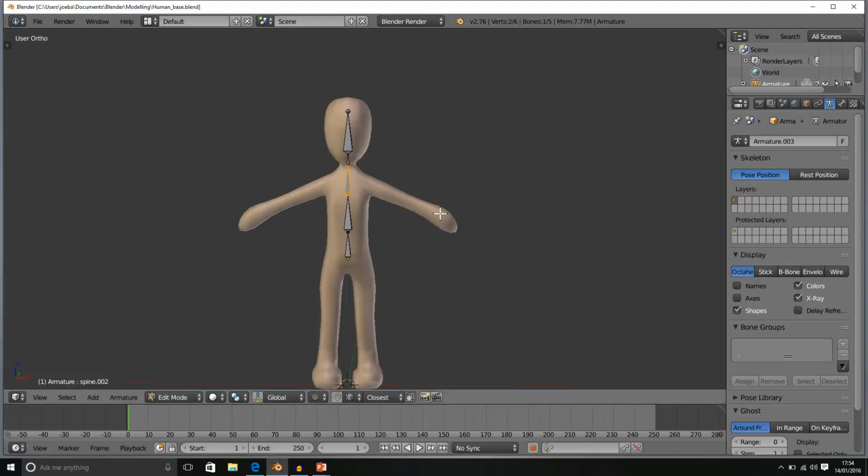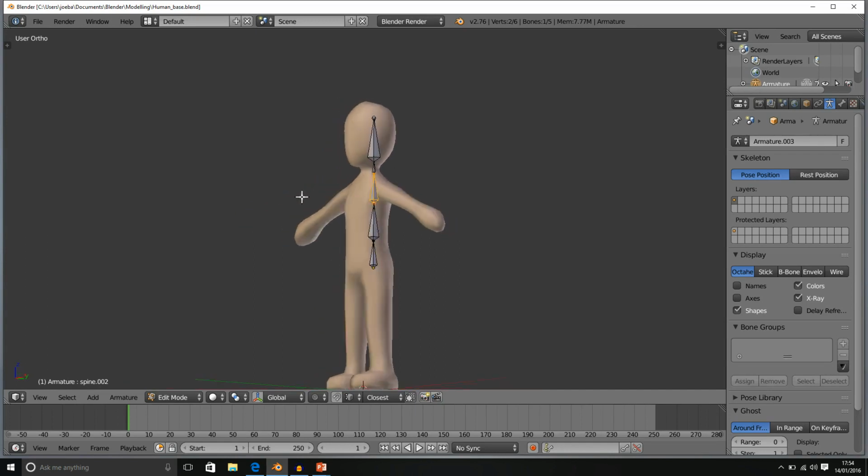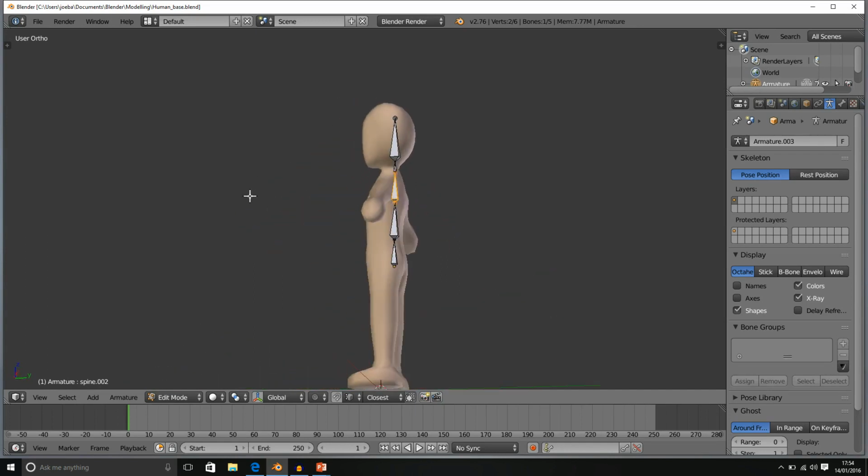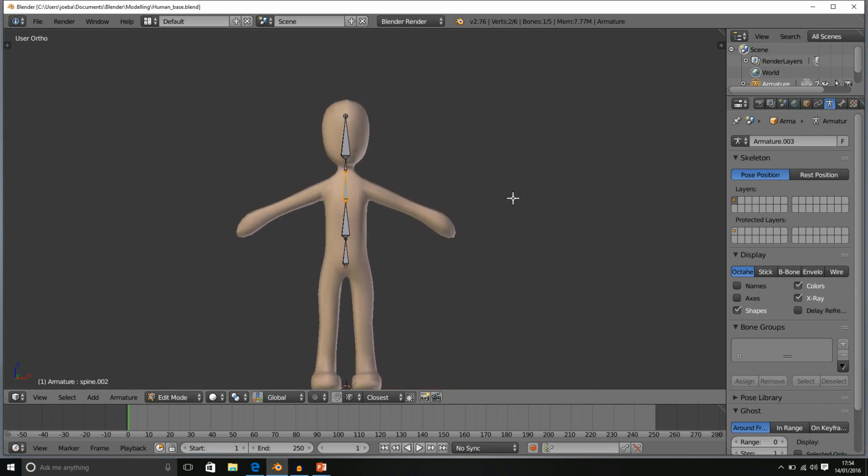So I'm going to go into Blender. At the moment we've got our spine, so we've got the bottom of the spine, the middle, the top and shoulders, we've got the neck, and we've got the head. Now I'm going to make sure I'm in a front orthographic view. I'm going to click about here, so I'm going to position my 3D cursor here. So this is another point where the 3D cursor becomes very valuable, because you can use the 3D cursor to mark where you're going to start a rig of bones.